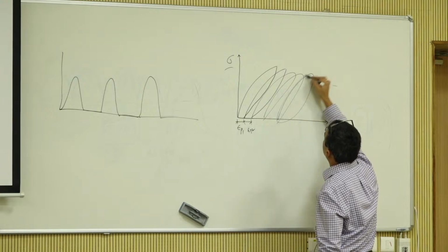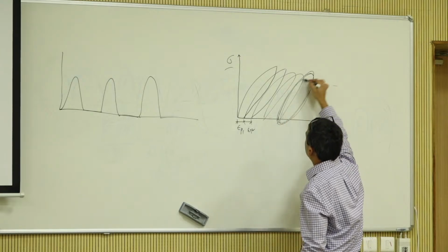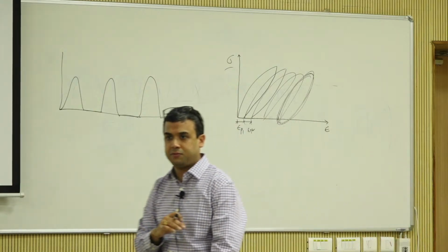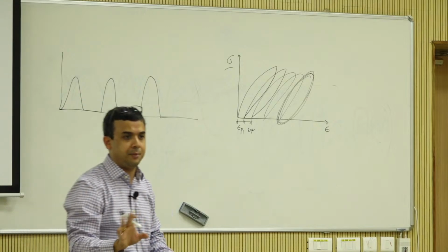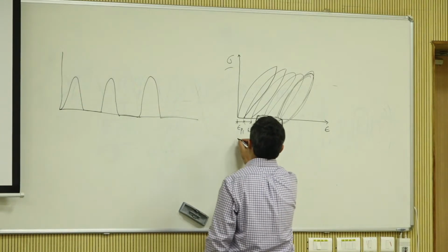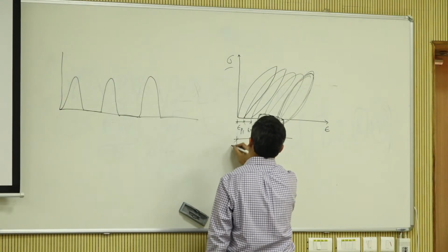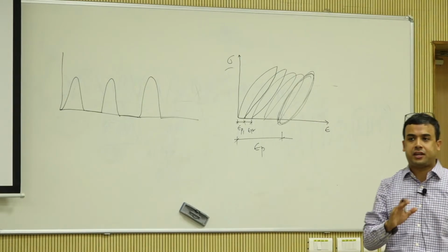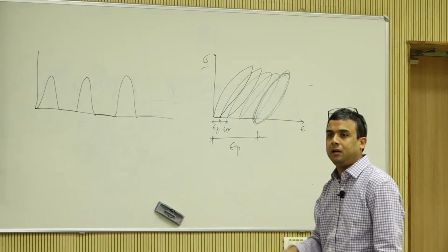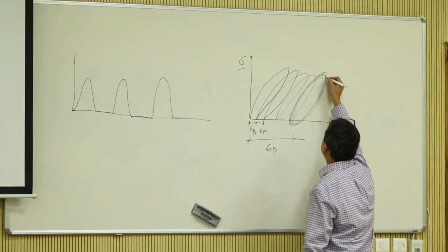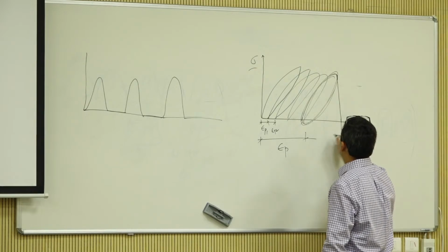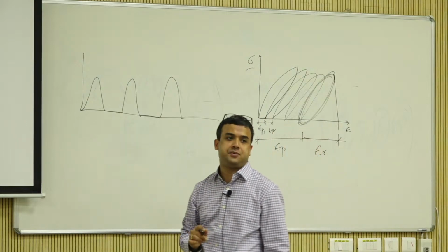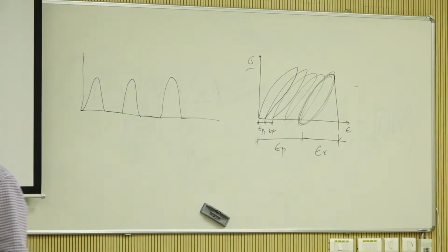Forever, a long time. After some time it is going to become what is known as hysteretic behavior. Whatever goes down, comes back. There is no additional energy dissipation happening. This amount is called the total permanent deformation that was accumulated on the sample because of all the loading. Then this is the recoverable part, or epsilon r, or resilient strain.